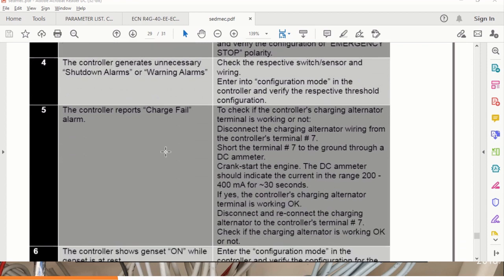Then, like a charger failed, alarm number 5. There is always a DG battery charger placed inside the DG set, which takes power from the grid and converts it into 12 volts, and then it maintains a standard threshold voltage, the float voltage, which is required to keep the DG battery always in a charged condition. This nominal voltage we have to set during our configuration master file.